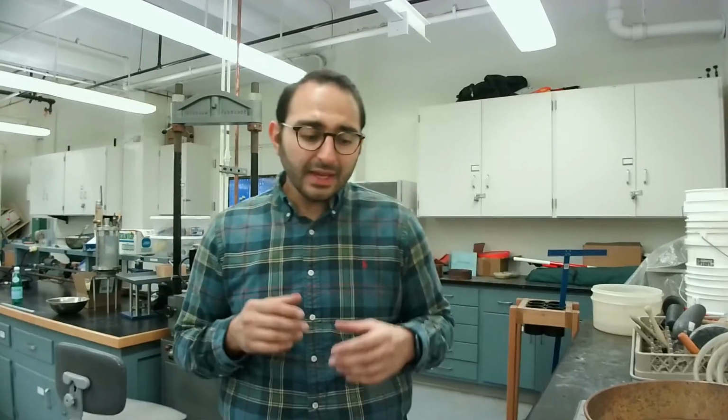The first thing that we need to do is to do the wash analysis. And during the wash, what we want to do is, through rinsing water inside the soil, grab all of the fines contents or the fine portion of our soil. So basically anything that will pass through the number 200 sieve, right? We want to grab all that separated from the coarse particles.